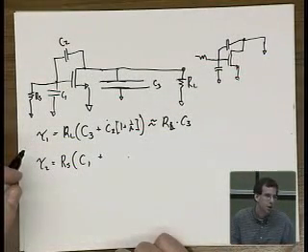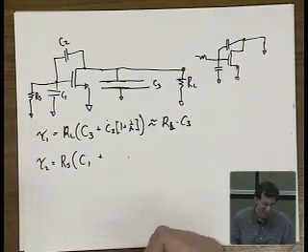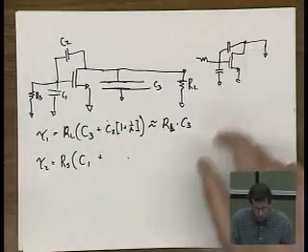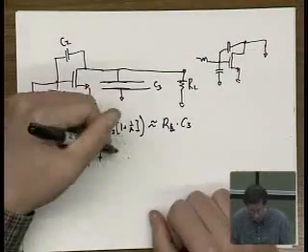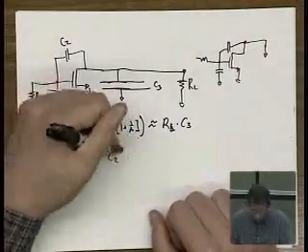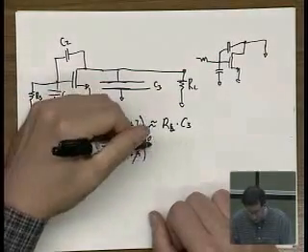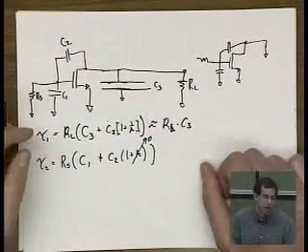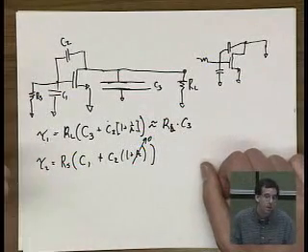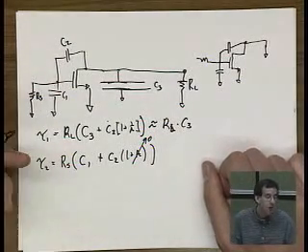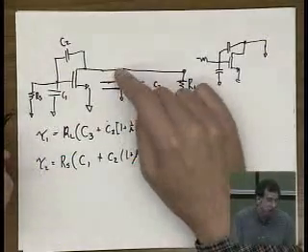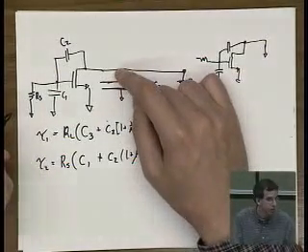Okay. So there is some Miller effect, but not really. And you can make an approximation that there is no Miller effect. So you get C1 plus C2, and you can still say 1 plus A, but A goes to 0 in the approximation here. Now you can see that I've made an optimistic approximation. I've assumed that this node is a ground, that there is no Miller effect.